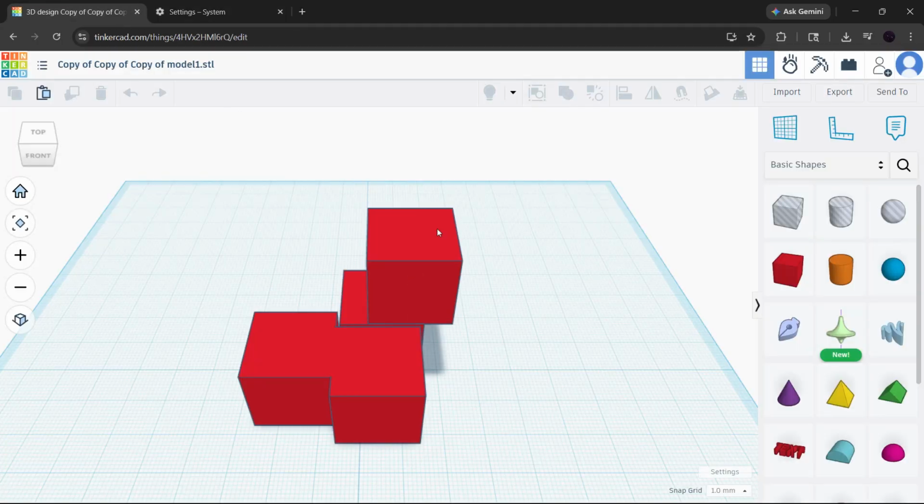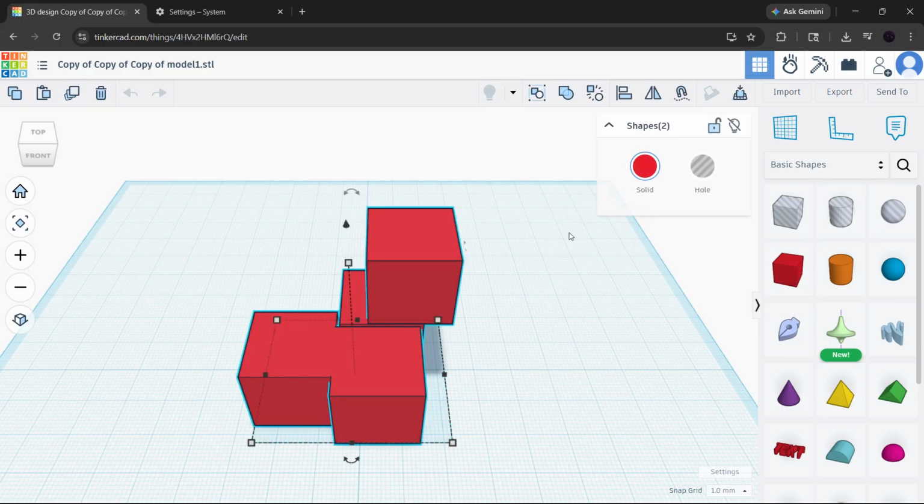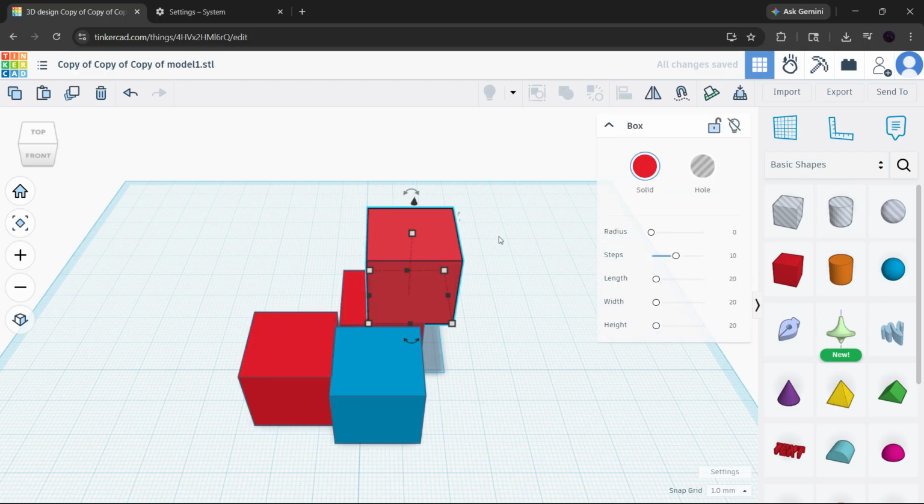So to quickly recap, if Tinkercad gives you an ungrouping objects error, start with the duplicate reset, then check whether the object was flattened into a created shape. Then try ungrouping one layer at a time. Use Ctrl+Z when possible, duplicate stuck generator shapes, and finally refresh your browser or turn on hardware acceleration if the display is lagging. One of these fixes usually solves the issue.